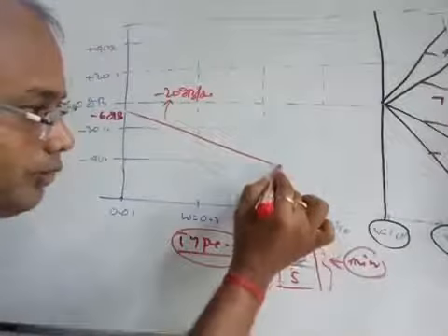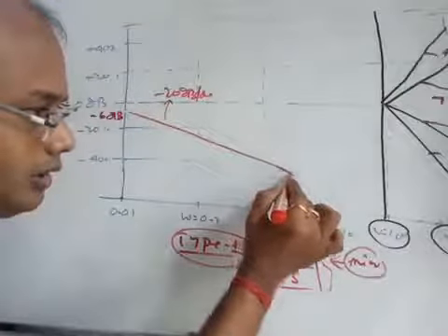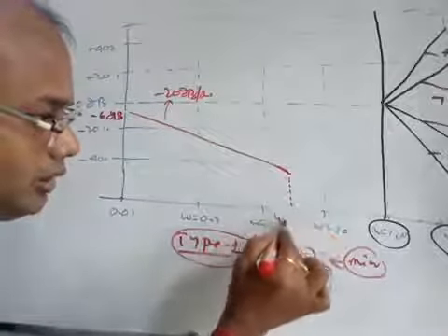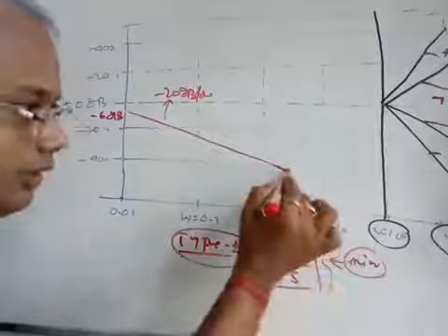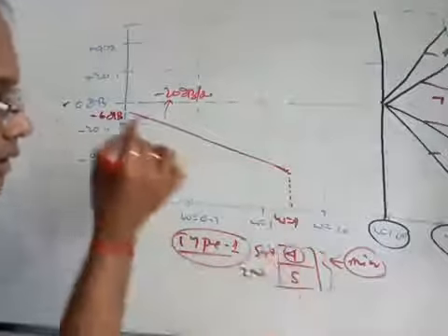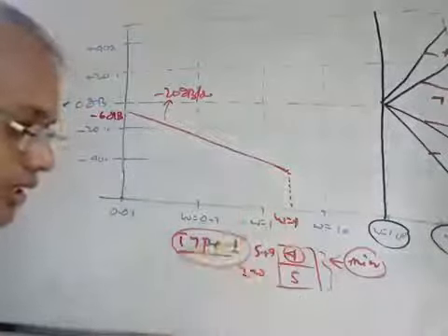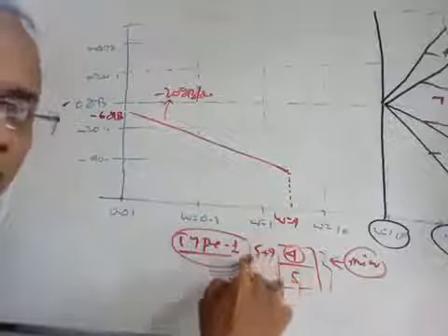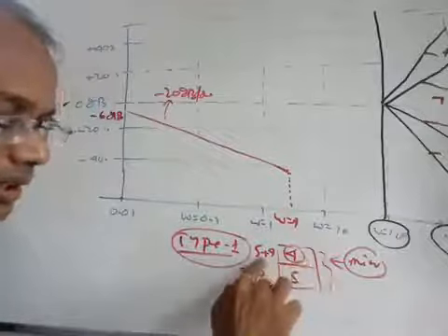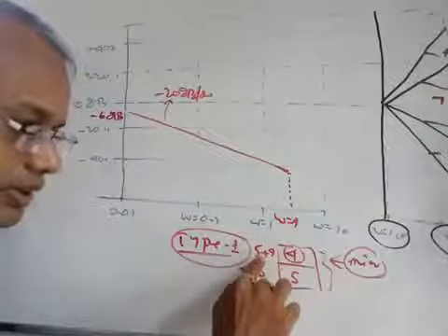So this is omega equal to 4, that you can get from this graph, and up to this the curve reaches. Once it reaches this, what it sees again is the factor s plus 4, corner frequency 4, and this factor is a pole.